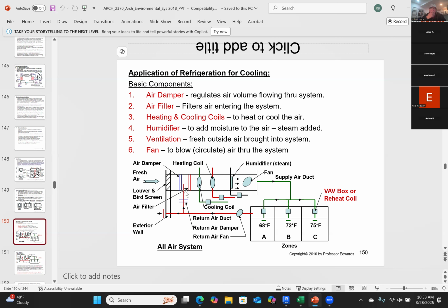This is how we've done it for decades. We've sent some of that occupied air back because it's conditioned and used that energy to heat the rest or to cool the rest of the incoming air to bring it up so that there's less of a delta T. Remember, less delta T means less energy to be put in there and then recirculate that back into the space. That's frowned upon now. So we take this whole return concept air and send it right straight out.